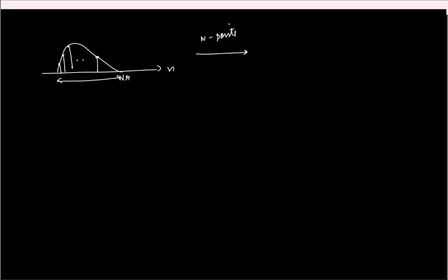Okay. So what happens if I take some discrete time sequence? This is a discrete time sequence, though I am drawing it as a continuous time signal for simplicity. Let us say this is a total of NR samples. I take the Fourier transform by taking N points, and then I reconstruct the sequence back. I'll have a periodic repetition of this, starting from N and so on. Again, these are all discrete time signals, drawn like a continuous thing for simplicity. So this is, let's say, NR minus 1. Fine. And here you can see that I inherently assumed that N is much greater than NR.